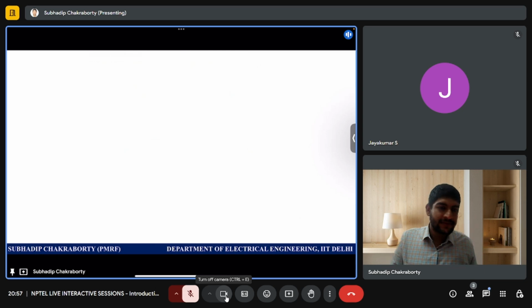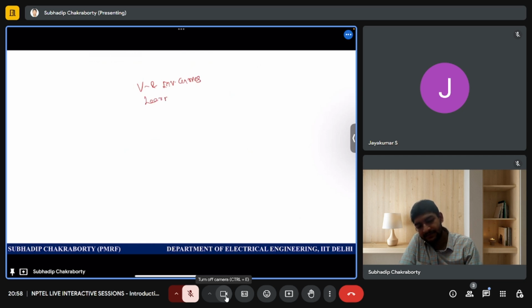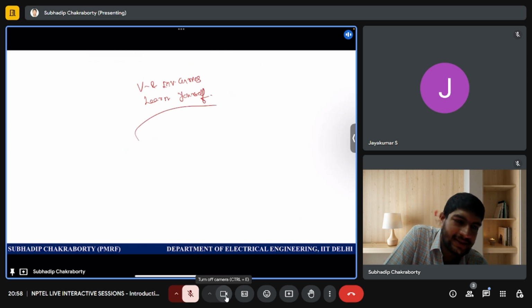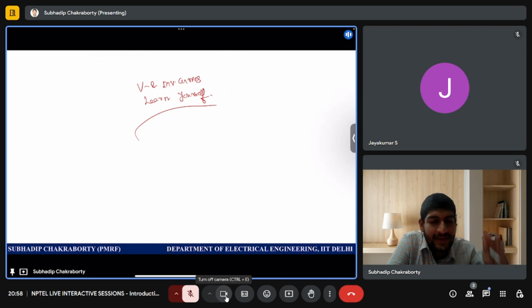Either way, you can remember the V curve, or better, you remember the phasor diagram, because in all the numericals, the V curves or inverted V curves will not help you. The phasor diagram only will help you, and the power angle equation and the equivalent circuit. Otherwise, nothing can help you. So you can learn the V and inverted V curves yourself, and I have no comments about it because they are not so helpful in solving the numericals. But all the conclusive results that we summarized can be found from the V and inverted V curves.